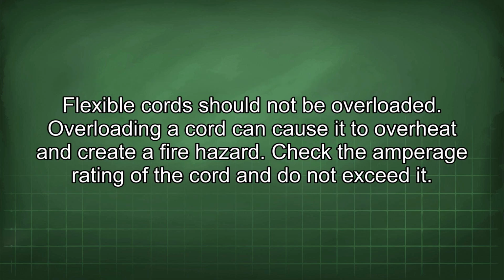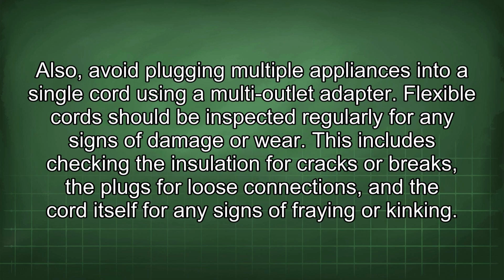Flexible cords should not be overloaded. Overloading a cord can cause it to overheat and create a fire hazard. Check the amperage rating of the cord and do not exceed it. Also, avoid plugging multiple appliances into a single cord using a multi-outlet adapter.